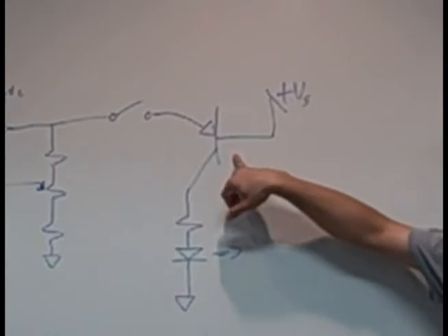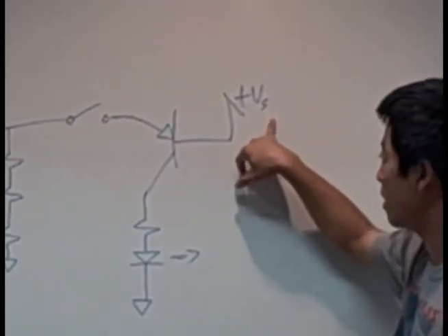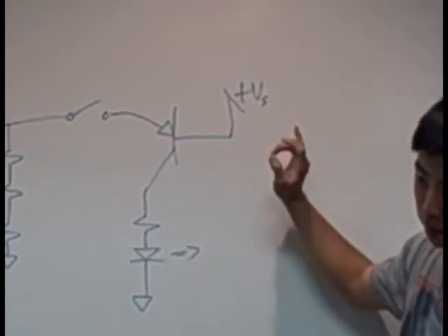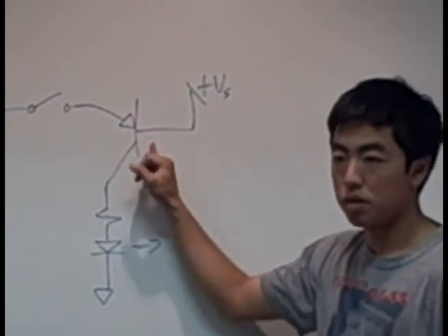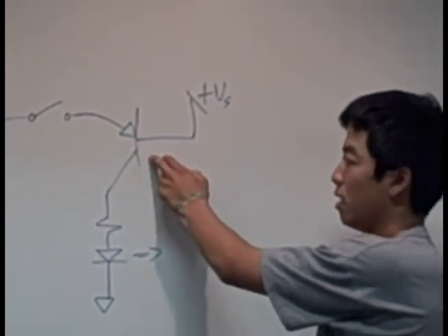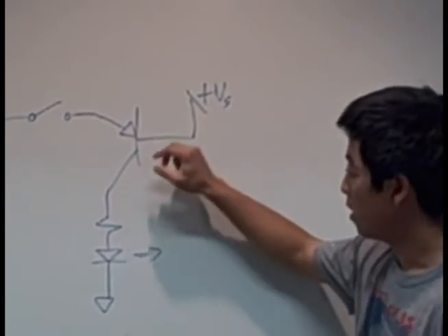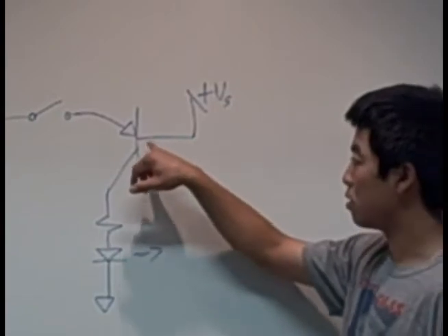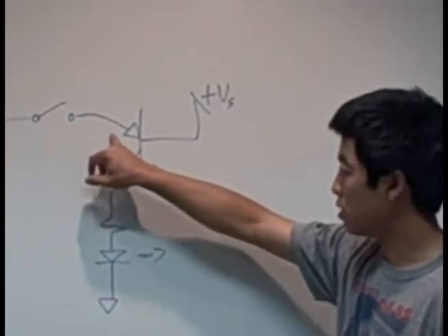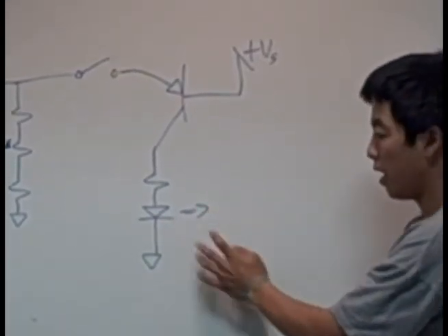and this PNP transistor is turned on when the voltage source of the solar panel outputs a low, so when the light is off. And when it's on, this will give the PNP transistor a high base input, and this will turn the PNP transistor off. So when the solar panel is off, it will turn this transistor on and allow current and voltage to flow through into the LED, thus turning it on, and that's our illumination circuit.